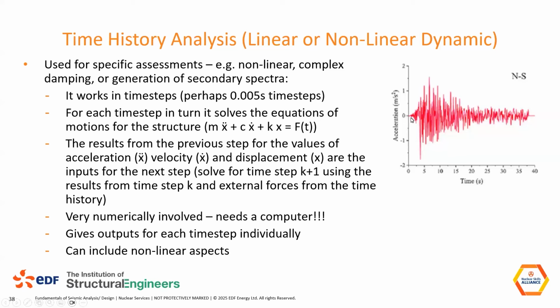And remember, we are doing this in 3 directions at the same time and combining them. And our time steps may well be around 0.005 seconds. Obviously, the smaller you make the time step, the more accurate the results. But if this is a 40-second event, and we're talking 200 per second, so yeah, 8,000.